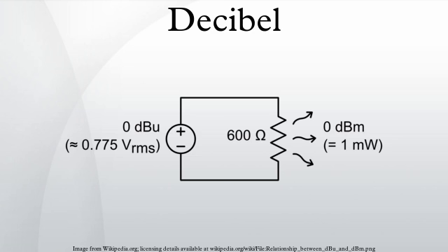Examples. All of these examples yield dimensionless answers in decibels because they are relative ratios expressed in decibels. The unit dBW is often used to denote a ratio for which the reference is 1 W, and similarly dBm for a 1 milliwatt reference point. Calculating the ratio of 1 kilowatt to 1 W in decibels yields the following. The ratio of √2 in decibels is the following. Illustrating the consequence from the definitions above that it has the same value, regardless of whether it is obtained from powers or from amplitudes, provided that in the specific system being considered power ratios are equal to amplitude ratios squared.